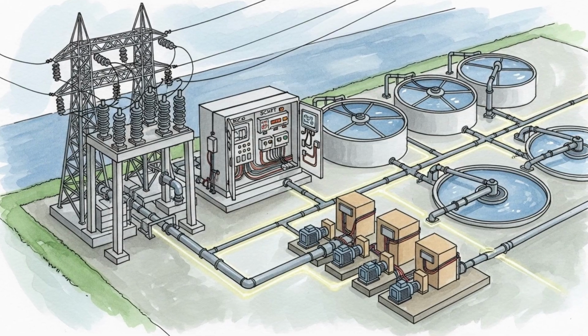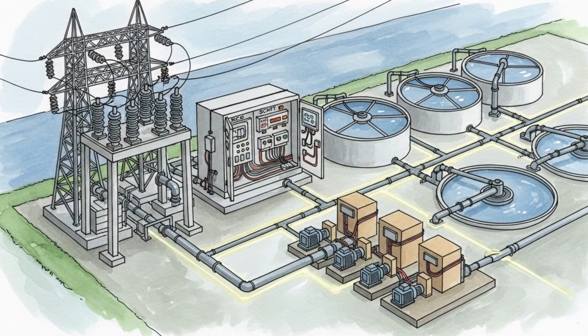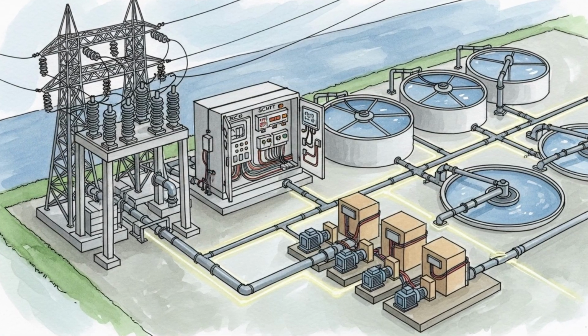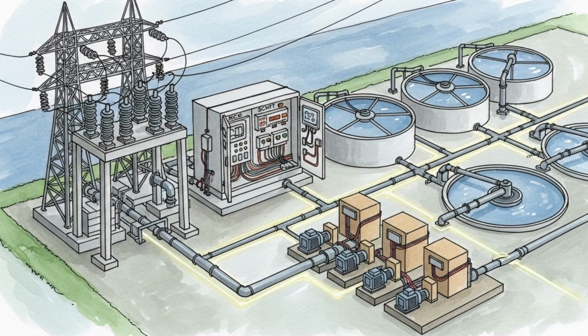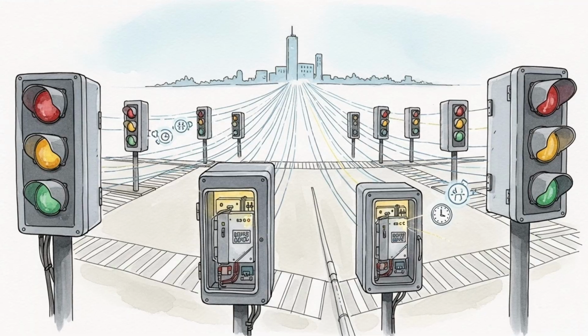Thermal time constants are long. A unit can tolerate short periods of stress, but may overheat if bias and loading persist. Dissolved gas analysis and temperature trends after a storm help detect damage that is not visible immediately.